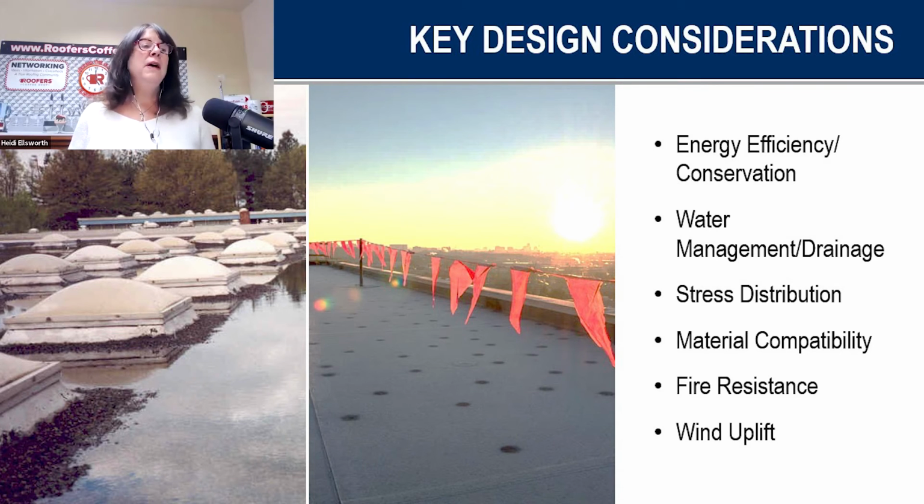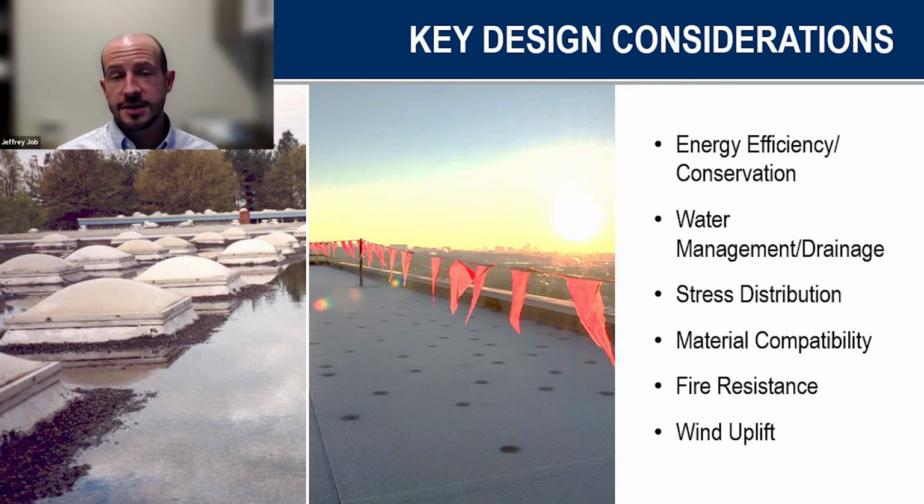Okay, let's talk about the ISO coverboard design, the benefits of that ISO. I know we talked a little bit about it before, but can you walk us through what the benefits of using that are? Yep. So I would say most of the ISO coverboards out there are going to be pretty similar. It's high density polyiso, a coated glass face coverboard, and that can drive a lot of different things.